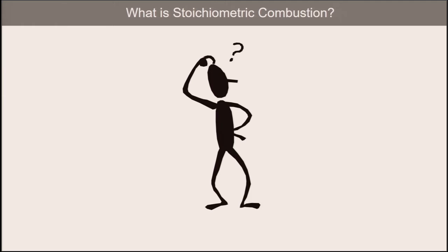But okay, getting back to combustion, I'm sure many of you have heard the term stoichiometric combustion, or maybe you haven't. Well, if not, it means 100% complete combustion where there are no hydrocarbons or soot that remain, and there's zero excess air, and there's no CO or carbon monoxide. Well, everything has been volatilized cleanly.